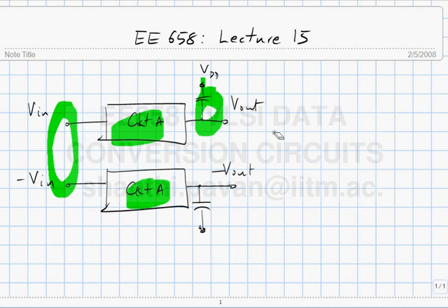From now on, all our signals of interest will be not one signal but two signals, and the reason to do two signals is what I just described. So our circuits will have differential inputs as well as differential outputs. We don't have to get too worried about the fact that this circuit is talking to the next circuit. It's not really a problem because the next circuit also will take in differential inputs. The entire analog signal path is what is called differential. That avoids all noise on the common.